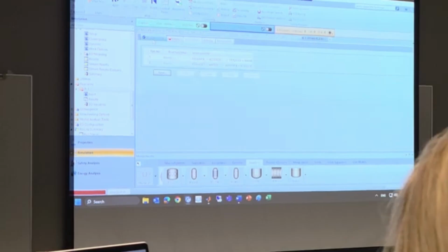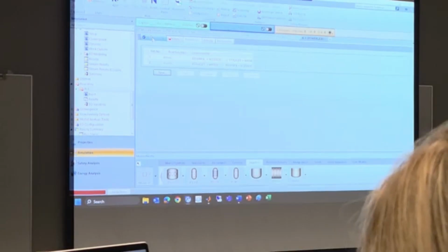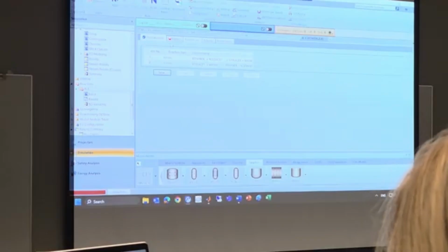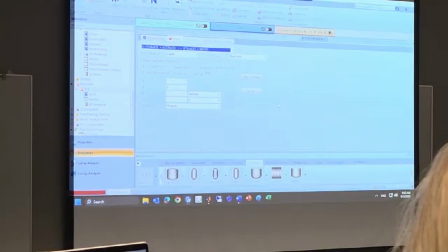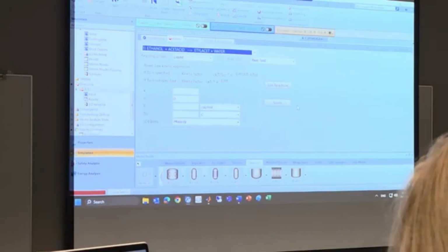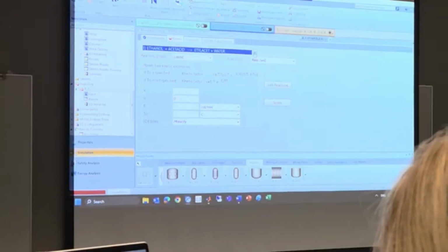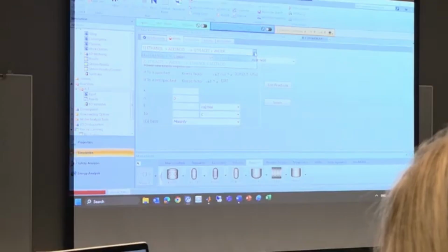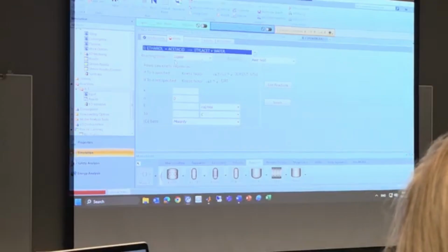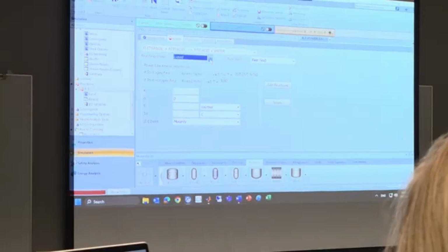Now we are working on the CSTR reactor, stoichiometry and kinetic. So if you go here to kinetic, can you see where? Let me do an exercise. If you click this drop-down arrow, we have two reactions, and we are working on the first reaction. Reacting phase: liquid, vapor, different phases.